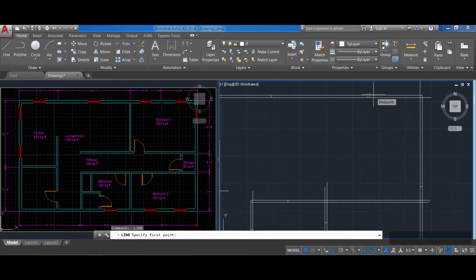So this is the 10.8, and this is the 8.9 marker. So I'm gonna go here, and I'm gonna go 14.8 according to that measurement there. So 14 feet 8. Enter. Okay, and then I'm gonna go right here. Just gonna press spacebar again, and here I'm gonna go all the way to this point. That's it. Now I need to do the inner walls again, so I'm gonna use reference points, 0, 5.